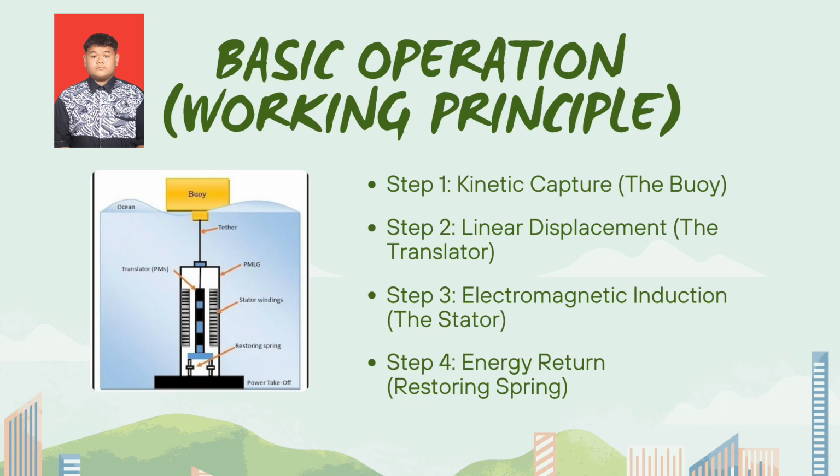It is electromagnetic induction. As the magnet moves past the copper stator windings, they induce an electrical current following Faraday's law. And finally, for step 4, a restoring spring at the base provides the tension needed to pull the translator back down as the wave passes. By using this method, we bypass the complex gears, making the system more efficient and durable in harsh marine environments.